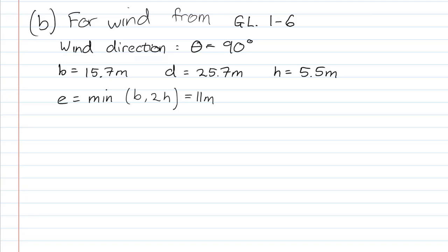So here we go, we've worked out the E value based upon shifting B and D around to adjust for the direction the wind strikes the building, or the direction that it is following through. Now we have to work out pressure coefficients on sides.